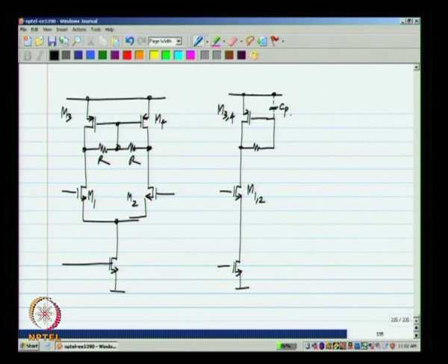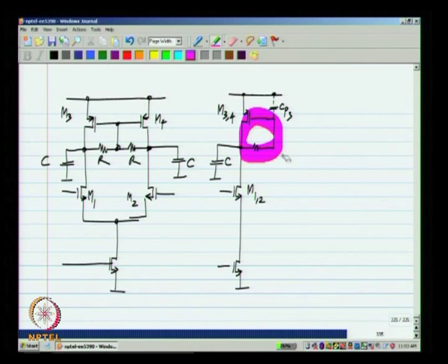okay. So, there may be some parasitic capacitance here, I will call it CP3, and then to make this into an op amp we will have the integrating capacitors C. Okay, we will have that. Now, in this feedback loop, the combination of M3, 4 and these capacitors, sorry, this should be 2C in the common mode half circuit, common mode equivalent circuit.